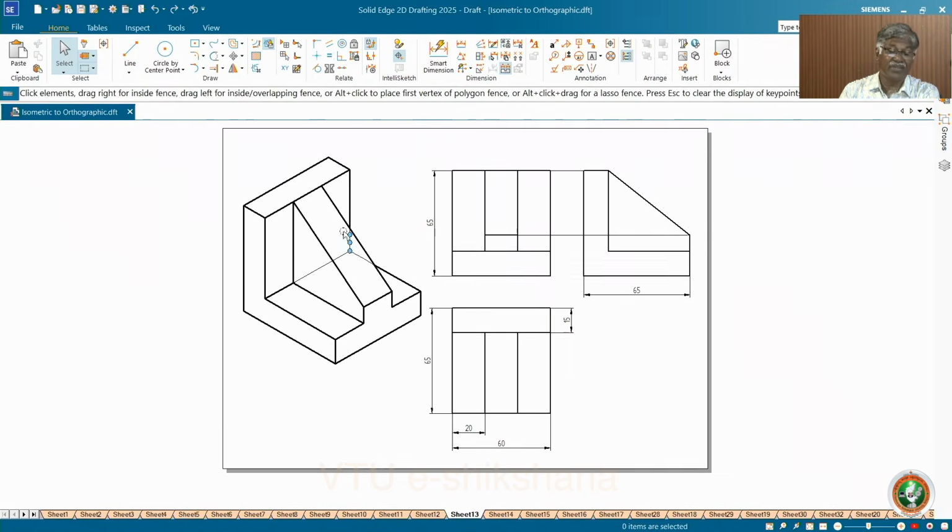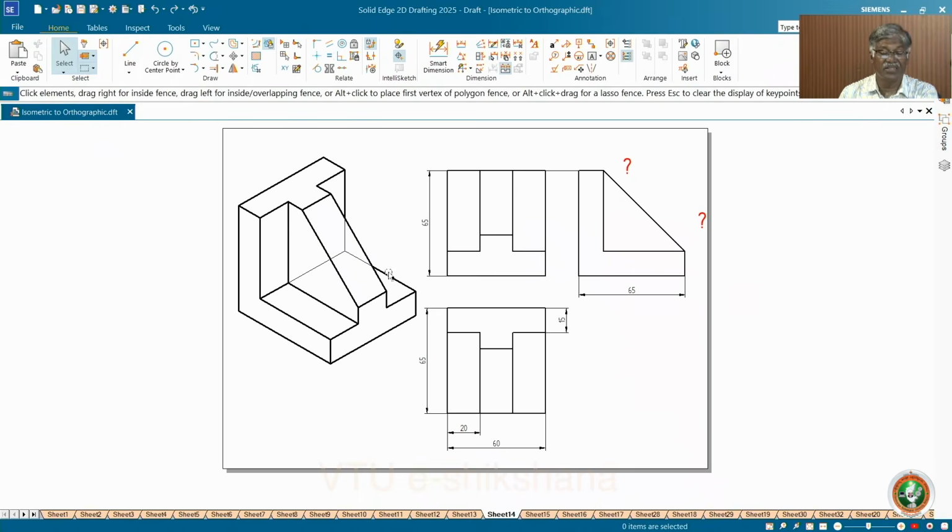Next, let me extend in the lower surface and also the top surface, both like this. Here I have done one each time. Now let me do both in a given time, extend here also and see how exactly it is. See, I have extended the top surface also by 10 mm for 20 mm width. Again, I have extended up the base block by 10 mm for width of 20 mm, that is mid width, web. I am changing only web size, web shape, that's all.